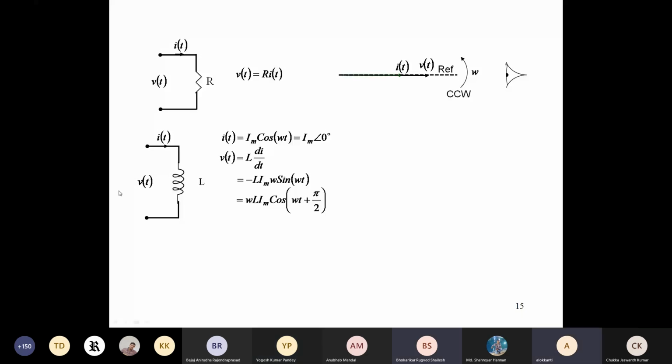In the last equation there will be a change, because in the second step we will not get minus. If you differentiate this cos, you will get minus. It is coming out of the differentiation. If we initially had minus L di by dt, then the minus would get cancelled. No, we are not keeping it initially because this is the voltage across the inductor. Even if we write KVL, V minus L di by dt equals 0, and bringing that to the right side, it will be positive. So it will turn out to be the same.